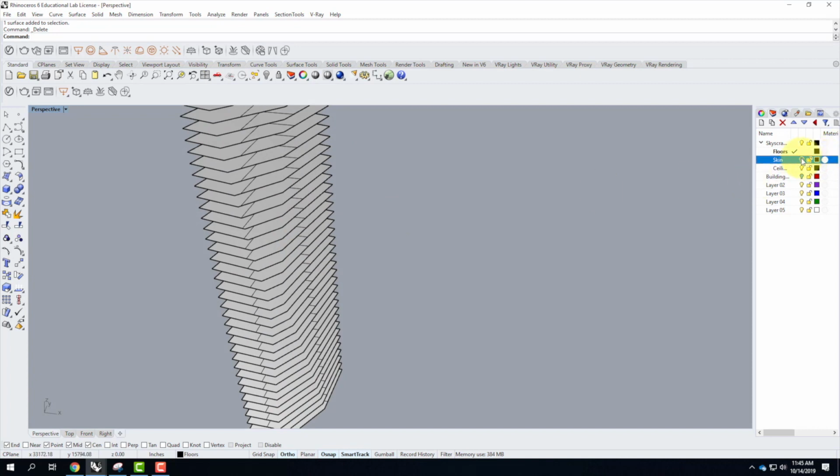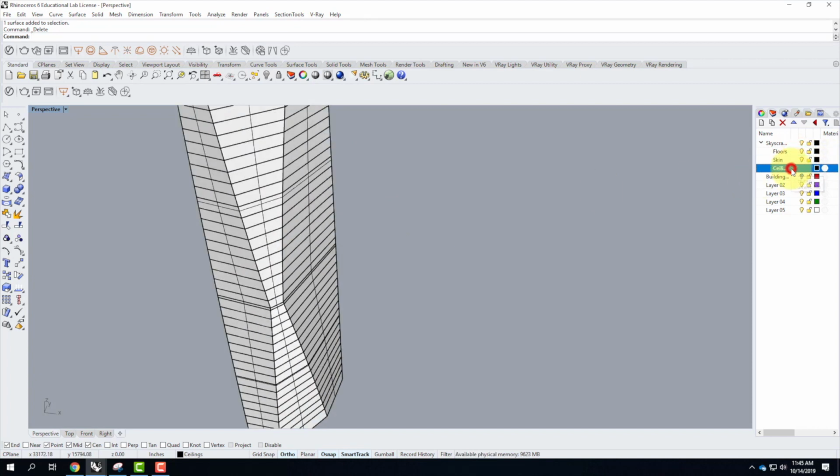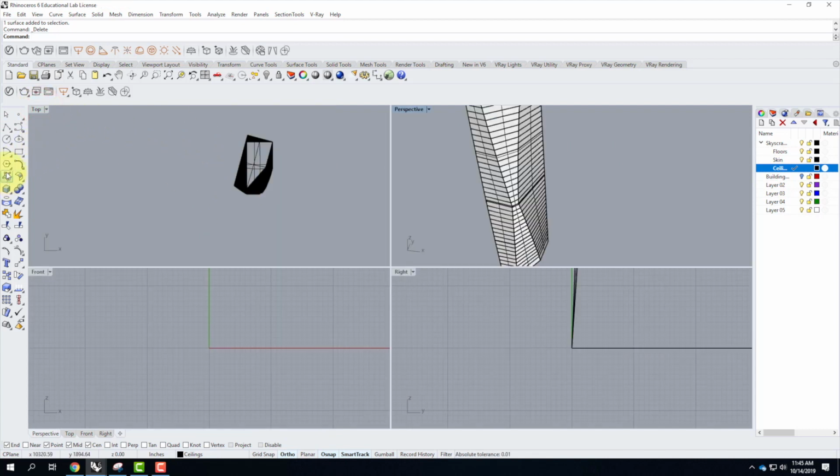So now it's time to do all of the ceilings. So we're going to do the same thing, but we're going to think about where the ceilings are placed. There's a reason that the ceilings are different than the floors, and that is because in a building like this, there is space in between the ceiling and the floor where the utilities go. The lights, the ductwork, all the stuff of the building, the structure of the building, etc. So I've given us 4 feet in there of space for those kinds of things to happen, the structure, the ductwork, and all that sort of thing.